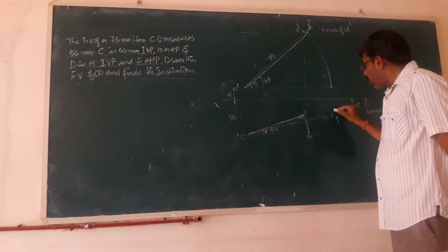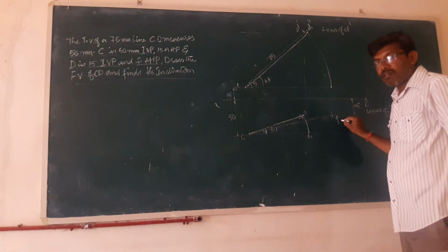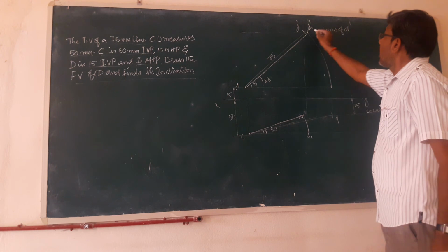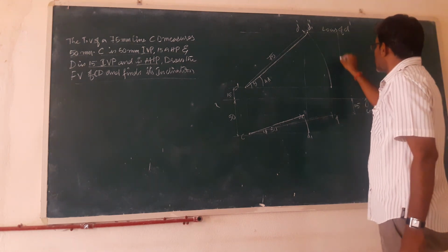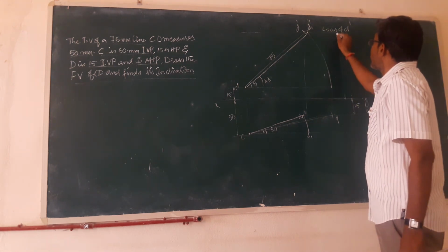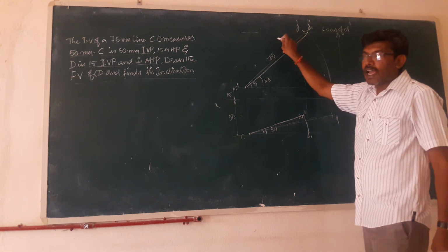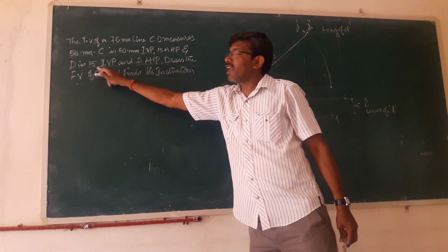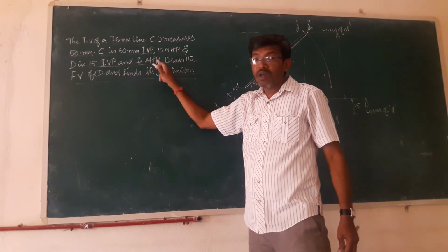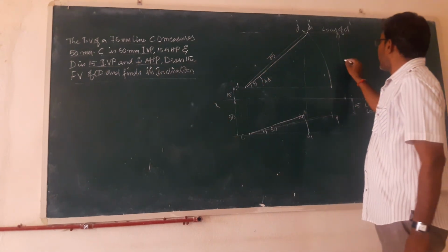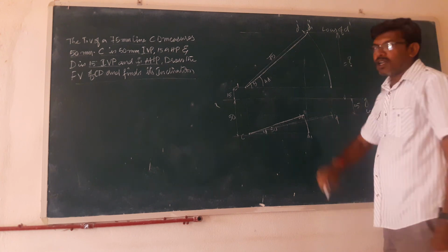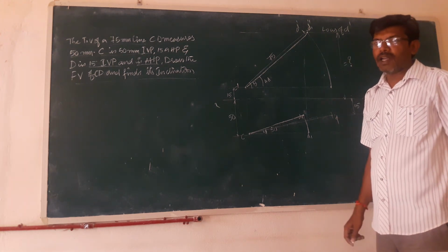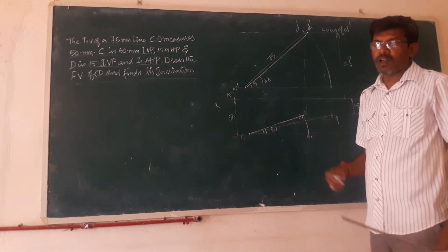And here point D is located in front of vertical plane and here I got a locus line here such that I will notice how much above. So D dash, because here it is given as D is 15 mm in front of vertical plane and above the horizontal plane. So I can find out the height of this particular point D that is above the horizontal plane.